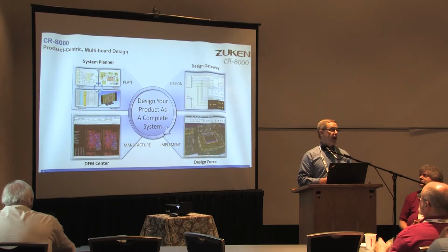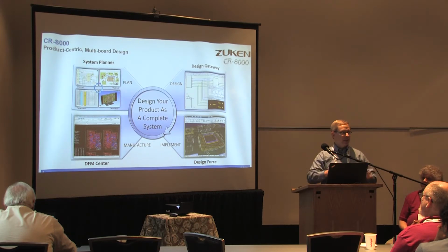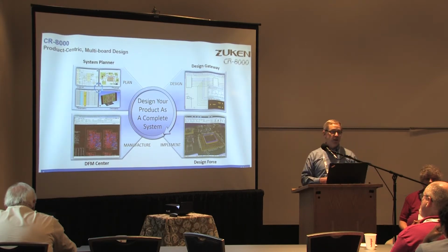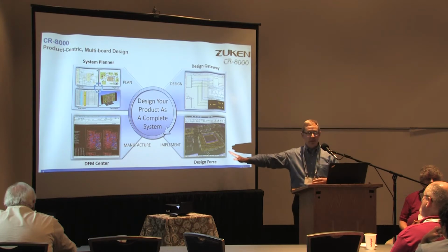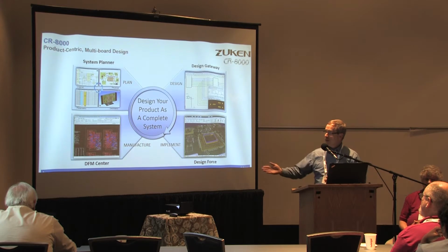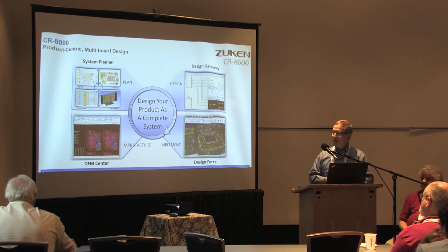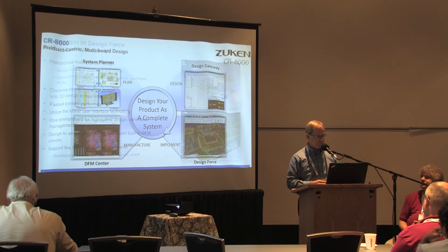CR8000 breaks down into four main sections. We have our System Planner, which is a block diagram capability to plan out your system, including MCAD capabilities. And then we've got Design Gateway, which is our schematic tools. I'm going to be focusing on Design Force. This is our layout tools, which, like I said, has been known as the PCB layout tools. But again, it's much more than that. And then we've got the DFSM Center, which provides tools that enable panelization and preparing your data for manufacturing. Again, I'm going to just focus on Design Force.